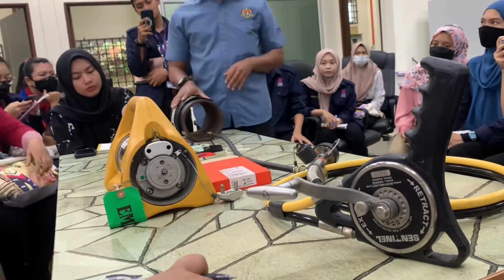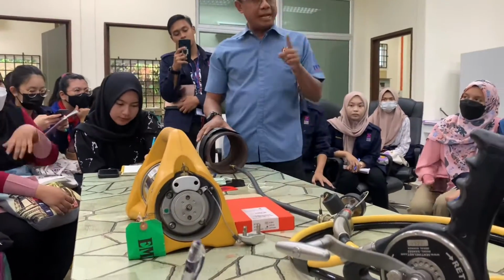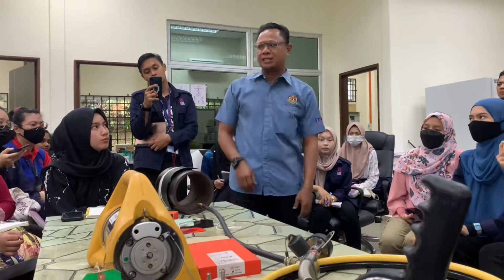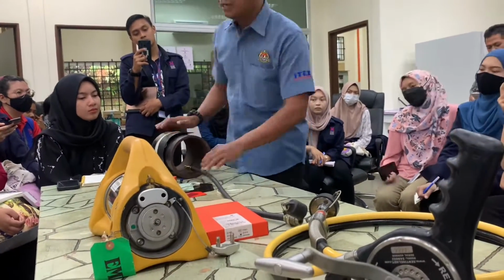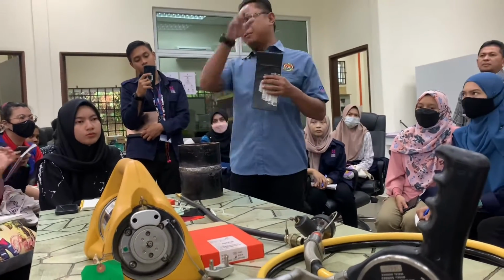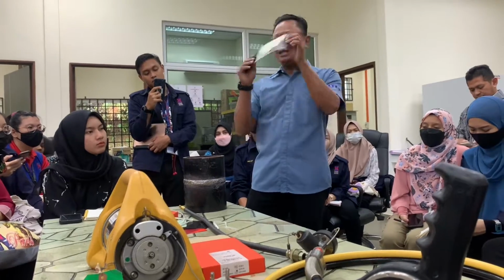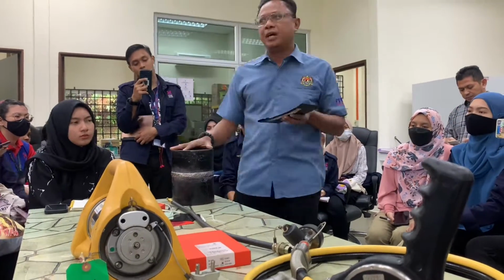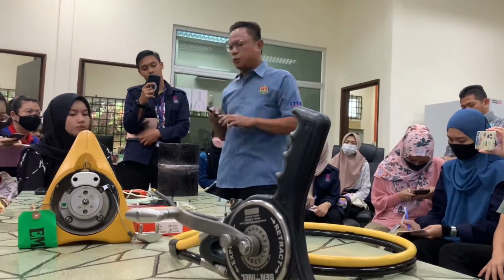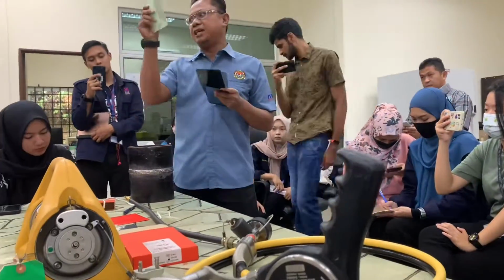In radiographic testing, the part to be tested is placed between the radiation source and a piece of sensitive film or detector. Once the X-ray or gamma ray radiation is started, the test part will hinder some of the radiation by its material density and thickness. Thicker and more dense material will allow less radiation to pass through the specimen.